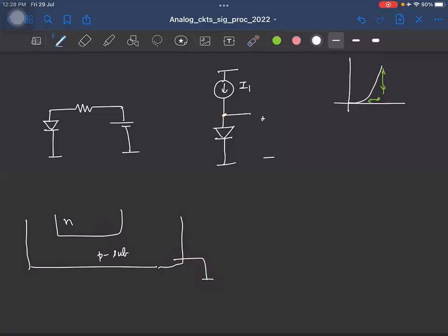So what you'll end up doing is you'll have one more P structure like this, and then realize a diode between these junctions. But as you can clearly see, you have a PNP transistor formed like this, right? So this is your P, N, and P, okay? So this is usually the case in CMOS process. It is kind of difficult to get an isolated diode, okay? Most of the time, you might end up getting a parasitic vertical bipolar transistor.